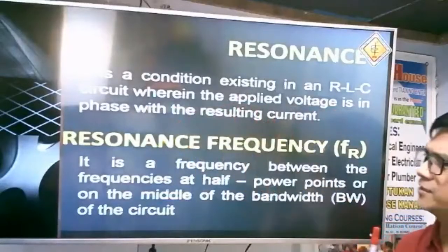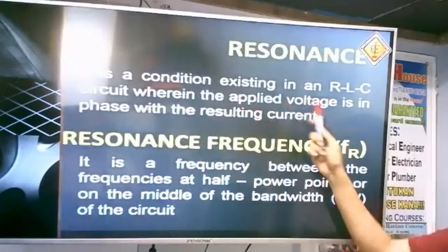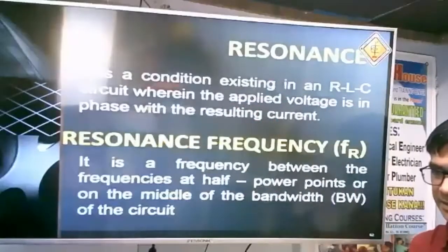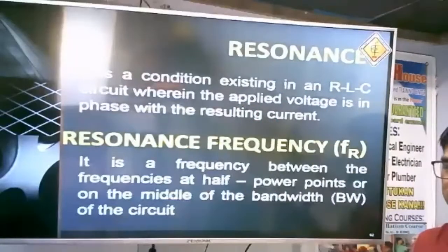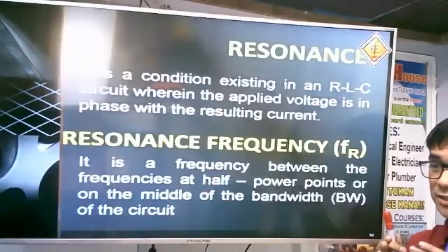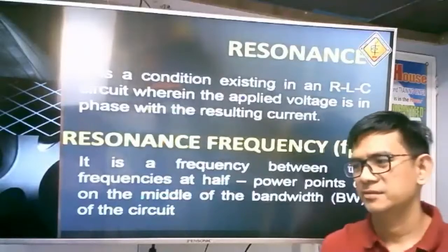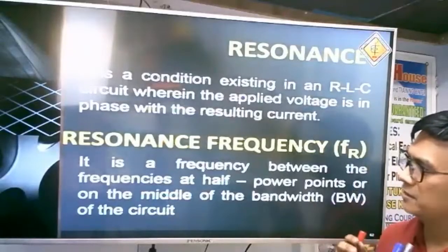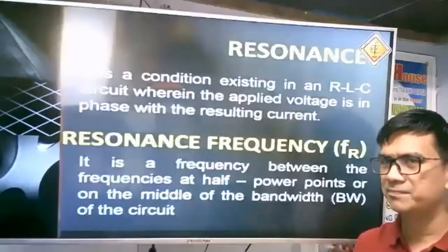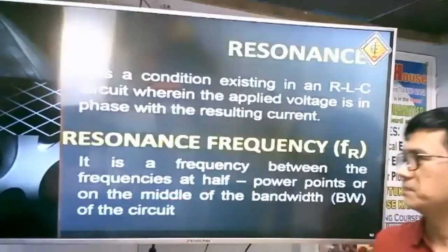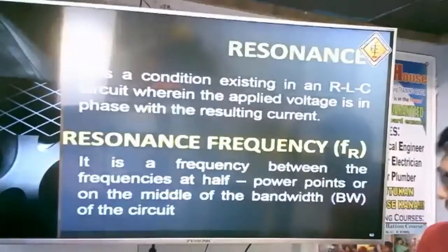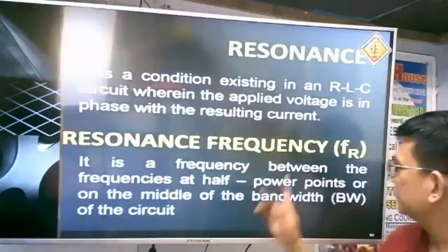What is the nature of this circuit? If the applied voltage is in phase, meaning the power factor is unity. There will be unity power factor because they are in phase. The circuit becomes purely resistive for the resonance condition.